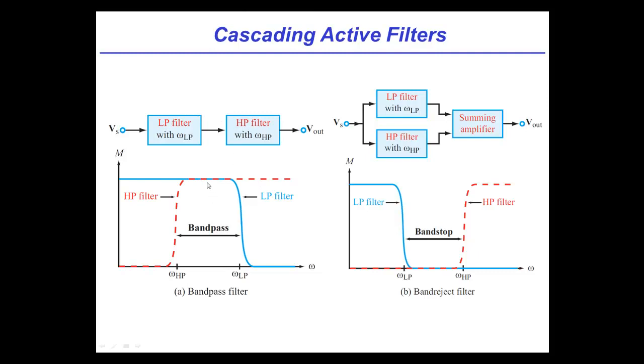That's right. Because each one kills a little bit of it. Correct. And then remember, if we were trying to do this just passively with multiple RC circuits, when you're calculating the transfer functions, it's not as simple as it was earlier. There can be second order interactions. That's right, because each op amp is effectively high impedance from the thing before. Exactly. Okay. Always thinking.